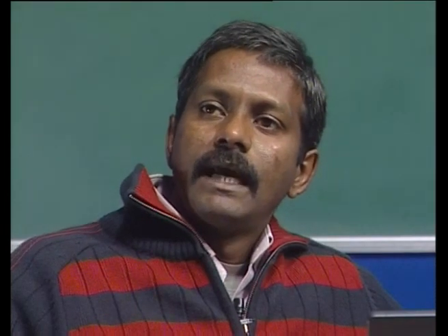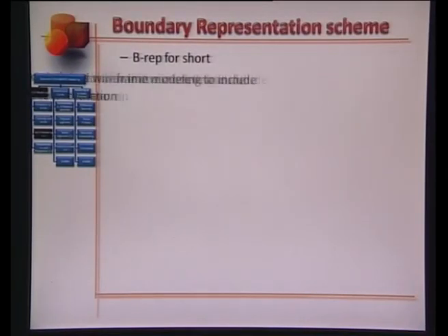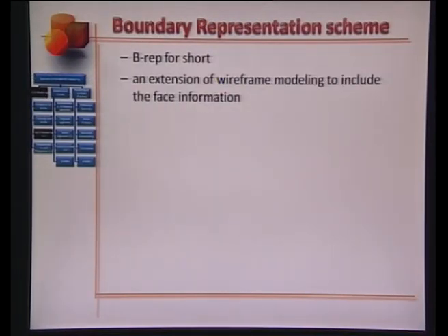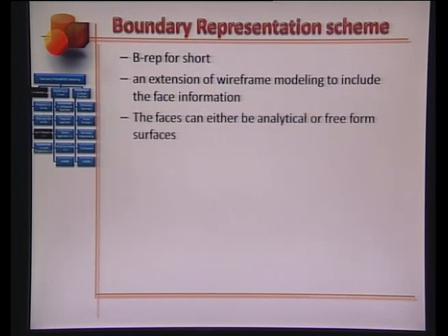The boundary representation scheme takes care of the anomalies in the wireframe approach. This is called BREP for short. And the boundary representation scheme is an extension of the wireframe modeling to include the face information. Faces can either be analytical or freeform surfaces.